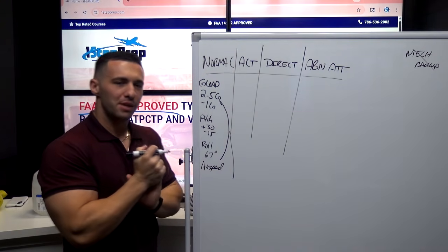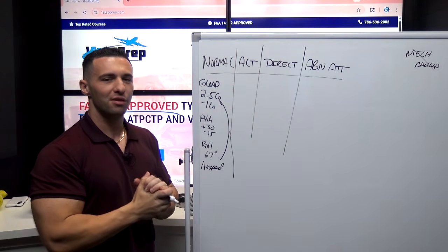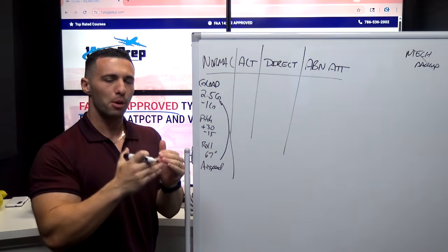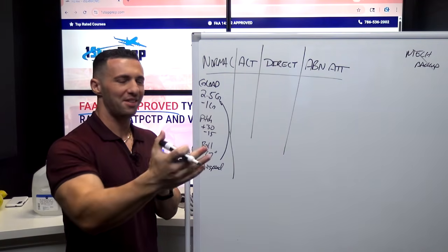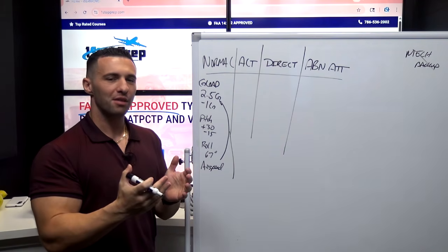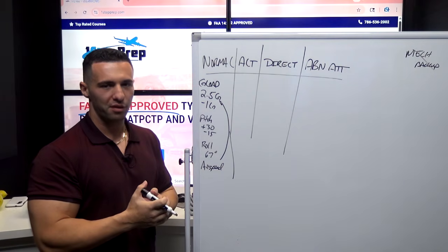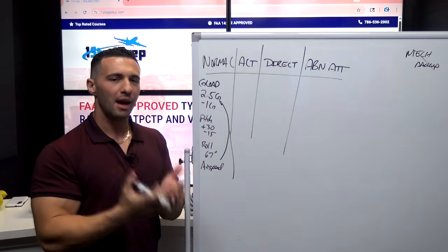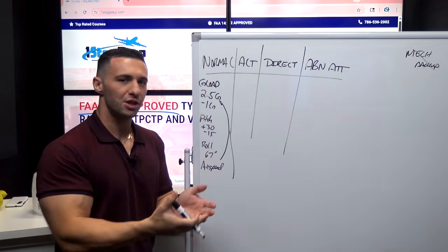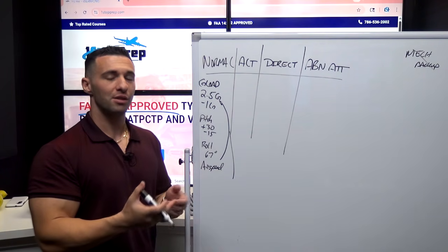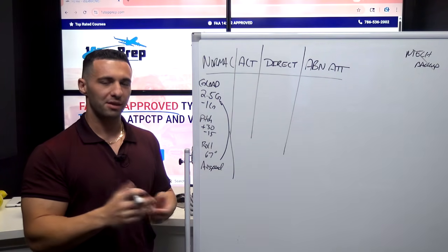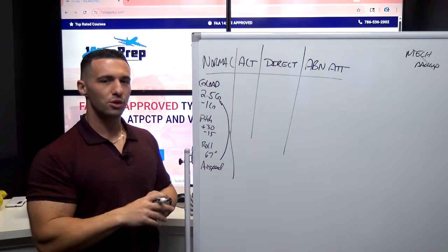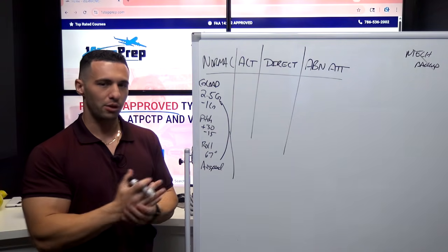And with the airspeed protection, what you want to know about this is there's two triggering events. There's VMO plus 4 and there's VMO plus 6. So plus 4 knots, we start to hear the aural alert of the overspeed, and then at plus 6, the actual overspeed protection activates its actions, one of which, of course, including the autopilot disconnecting and the nose beginning to come up in an effort to reduce airspeed.